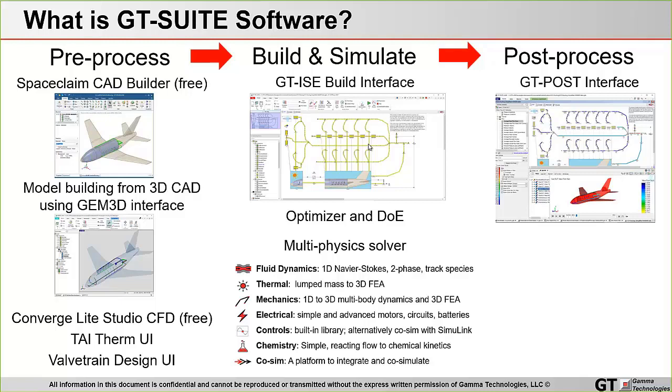But you can also integrate the fluid domain with a thermal domain, represented either with a lumped mass or 3D finite element approach. You can also integrate with mechanics for fluid structure interaction, for 1D to 3D multi-body dynamics, or 3D FEA as well. And then, as we're getting on the topic of electrified aircraft, and we'll be talking a little bit more about that later, we have the ability to simulate simple and advanced motors, electric circuits, and also batteries, either at the electrical equivalent level or at the detailed electrochemistry level.